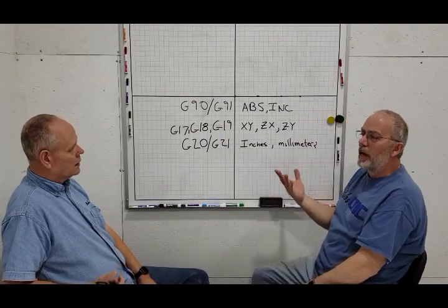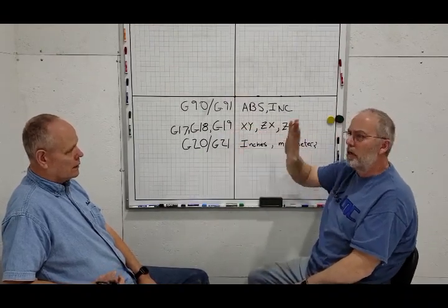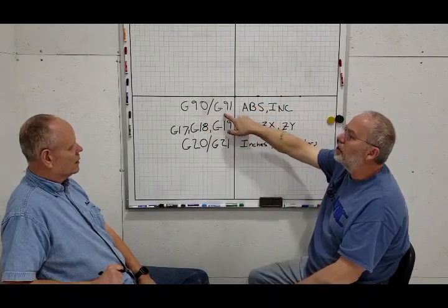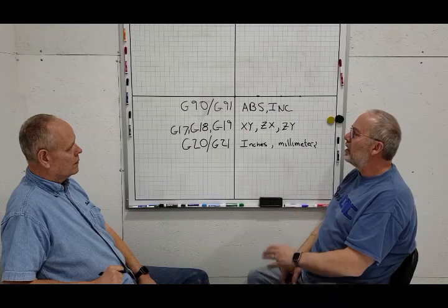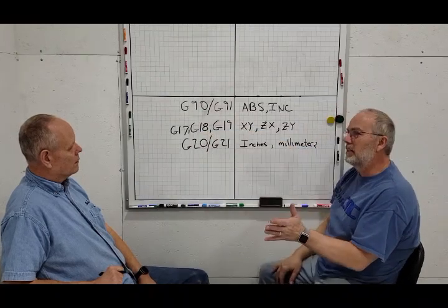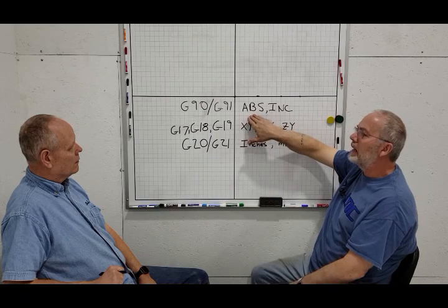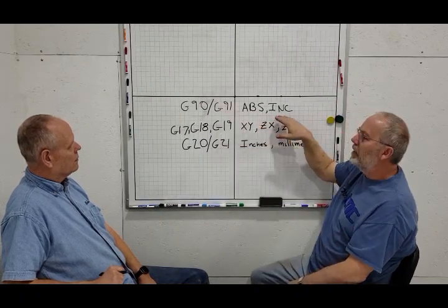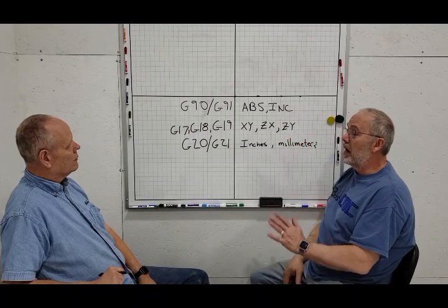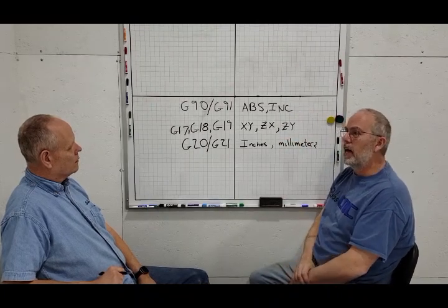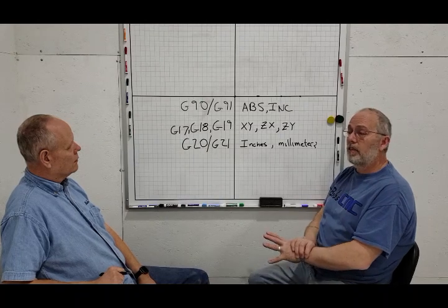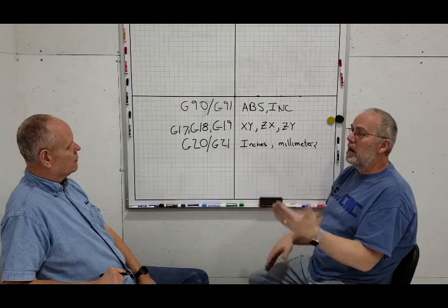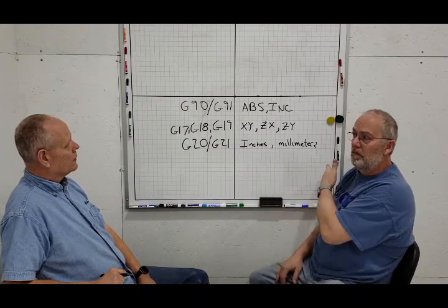The first G-code line you might find, and it may be on the second or third line, but don't get confused, it's just somewhere at the top of the file, is G90 or G91. Honestly, most of the time it's going to be G90, and that will make sense as we talk about it. G90 is the absolute coordinate system, whereas G91 is incremental. So in the G90 world, if it says X5, it's always 5. In incremental mode, it could be 5, 10, 15.